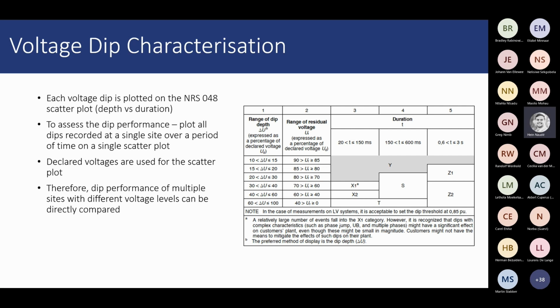So they're spinning a 60 MVA generator basically to ride through all the dips on the mine. They're using that as a mitigation, almost like a UPS, a rotary UPS. That's basically a running UPS, to provide reactive power support during a dip. That's one way of mitigating events here. Then capacitors, they have a big spinning reserve.